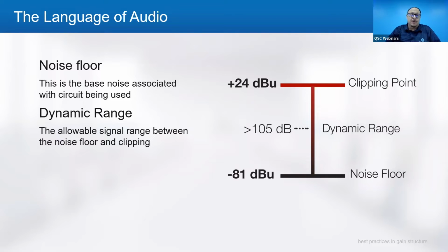This can sometimes also be called distortion or overdriving. Very cool if you're a rock guitarist, you're going to want to clip and overdrive your signal. That's typically done on guitar amplifiers: you overdrive the input gain stage, and then later on the main amplifier stage, you turn the volume down to control the overall volume, and you get your clipping there. Clipping in audio conferencing, however, and distortion is not something we typically look for. And so much of this is conferencing based, so we're going to stay focused on that.